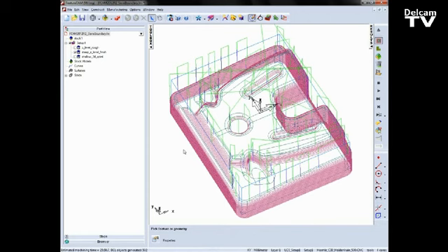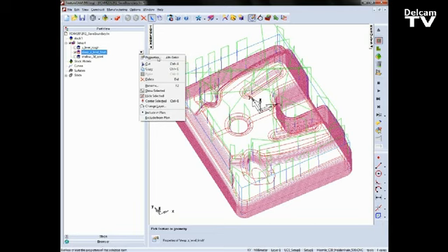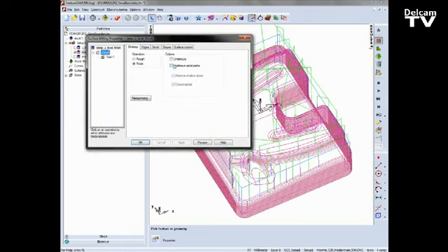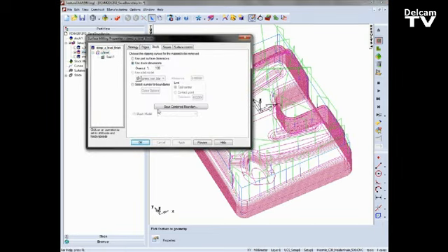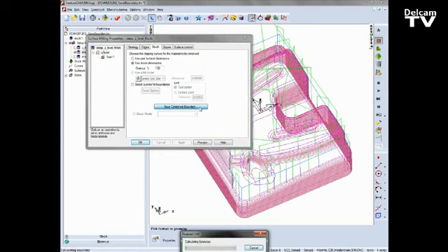If I want to use that same boundary, I can now obtain that from this feature and save this as curve information and use it for other operations. So in this case I've got a shallow toolpath that I'm creating. This is going to be a 3D spiral. So if I go into the steep Z level, into the Z level area, into the stock tab, you've got a save combined boundary, I can select that option,